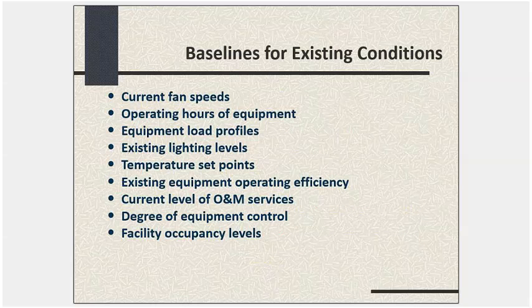So, when you characterize a baseline, sometimes people think, well, I'm just looking at a utility meter, or a short-term measurement of kW or something else. But I don't really need to be concerned about anything other than those short-term measurements of a circuit or the actual measurements from utility data. But actually you do, because a baseline for utility consumption does not exist in a vacuum. There's also the existing conditions, like what are the operating hours of that equipment?